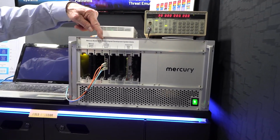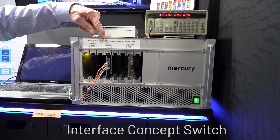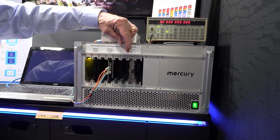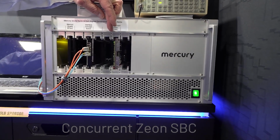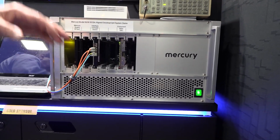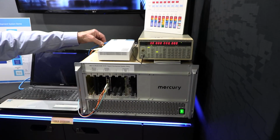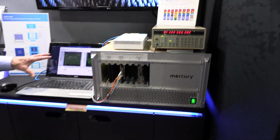Here we have a switch card from Interface Concept that connects Ethernet traffic across the backplane and also delivers 2 40 gigabit Ethernet optical links out through the front panel. Here is a single board computer from Concurrent that receives the samples from the switch card, does processing on it for signal analysis. The 2 optical cables are connected up to an external Ethernet switch on top. One of the ports of that switch is a 1 gigabit Ethernet copper that goes down to our laptop computer.